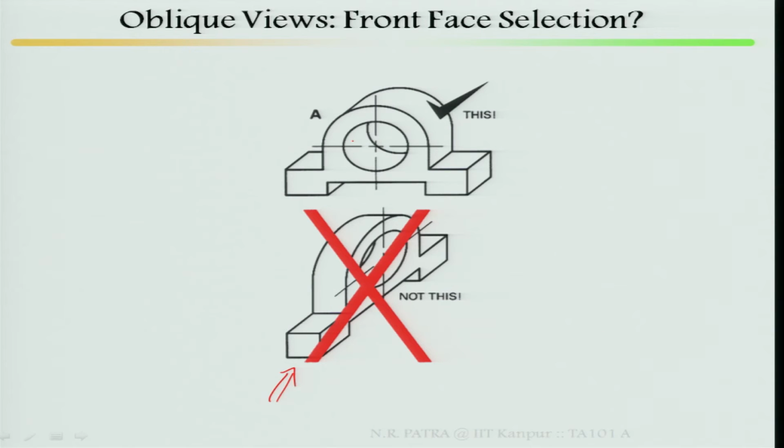Rule 2, longest dimensions. This is your longest dimension, you put it parallel to your picture plane, it should not be in your depth direction. So, considering rule 1 and rule 2, this is not a true front face.